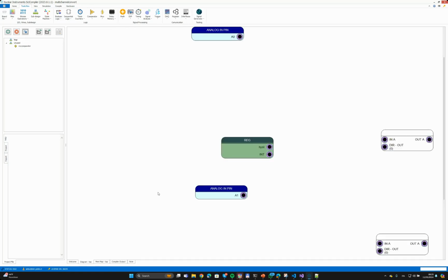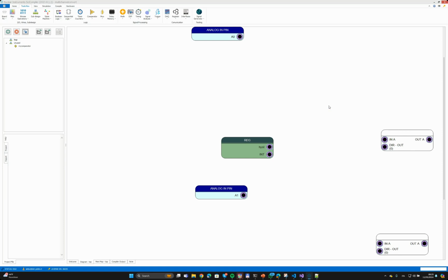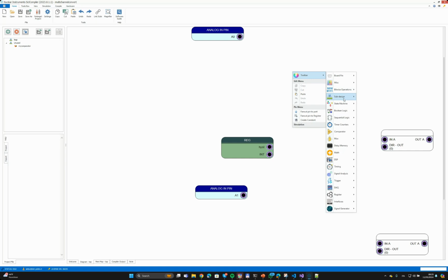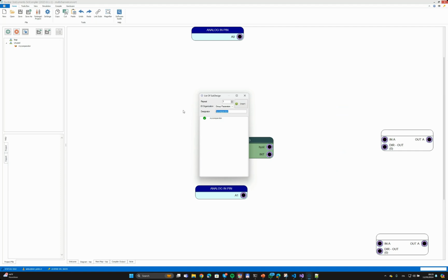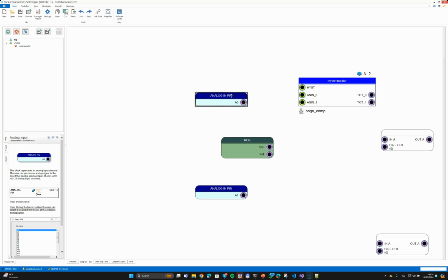and we select diagram. Okay, now we need just to place the new component. We go to toolbar, subdesign, multi-channel design. It says, oh, it's out of sync. Yes, because we needed to save the design in order to compile that page. Now we can go back to the subdesign, multi-channel. Okay, it's fine. We can call it comp, and how many times do we want it? Two channels, insert. Okay, this will be the name, the endpoint name will be page comp.